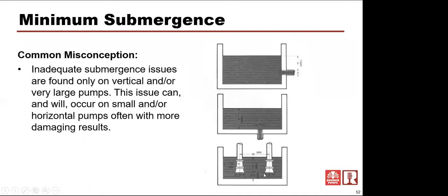The diameter of the intake is important because if you have 500 gallons a minute, for instance, going into a pump, it's all about what that velocity is. Well, the larger the diameter of this pipe is, the lower that velocity is. And there are charts to show that, or a mathematical calculation to show what that velocity is.